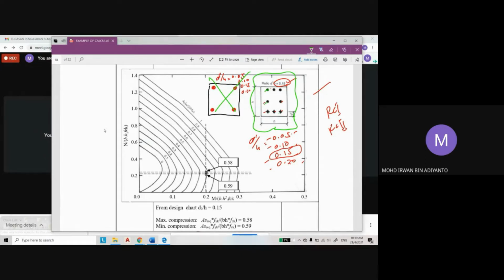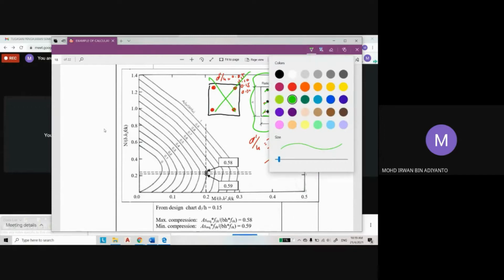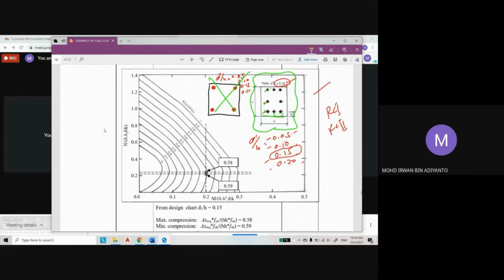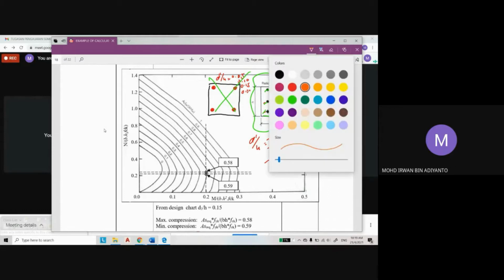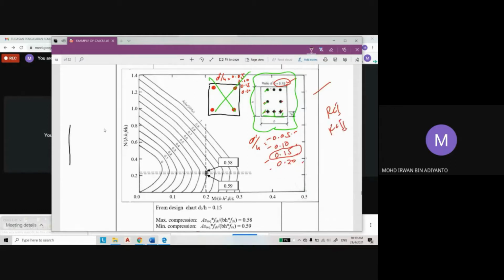At least you have three steel bars on every side, because in seismic design for the DCM and DCH categories, there is a requirement. The first condition is that you must have at least 3 bars in every side.